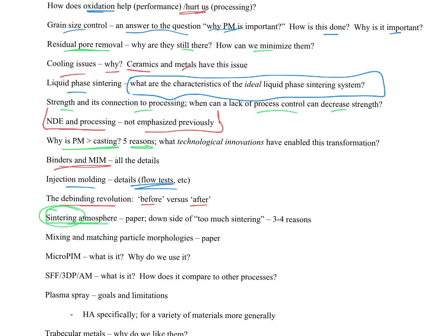There is such a thing as too much sintering, all right? So you should already have an idea of what that is, but in the context of metals, it's probably even more important because, again, there's this huge need for grain size control and other aspects of compositional control, making phases that shouldn't be there, all right? So you can't just have it sit in the furnace forever. It's got a limited ability to be in there, and the temperatures involved are also going to be limited.